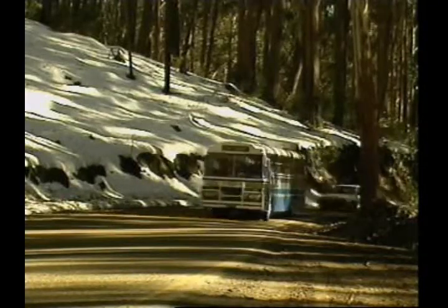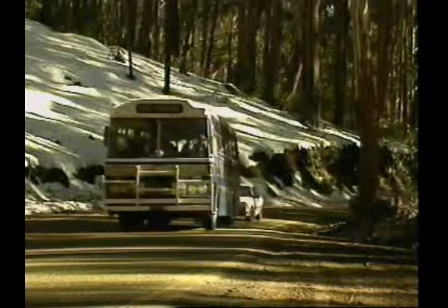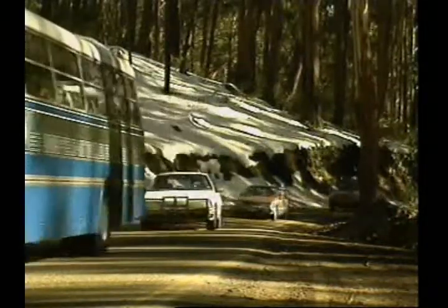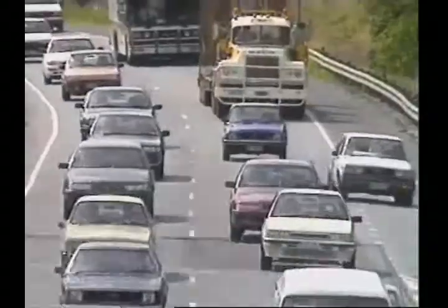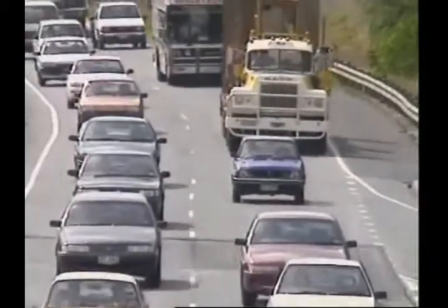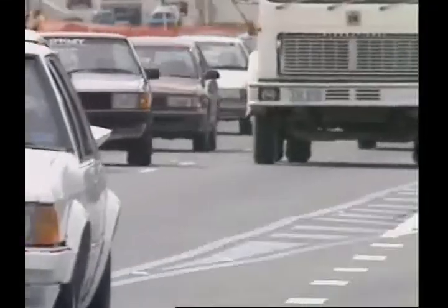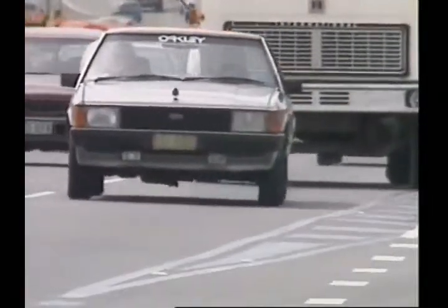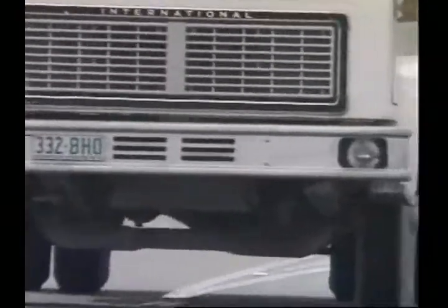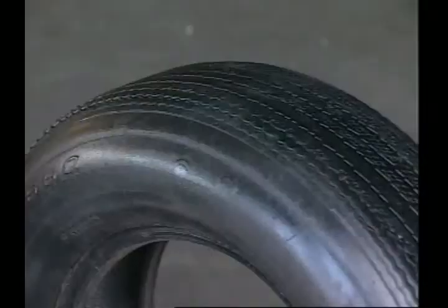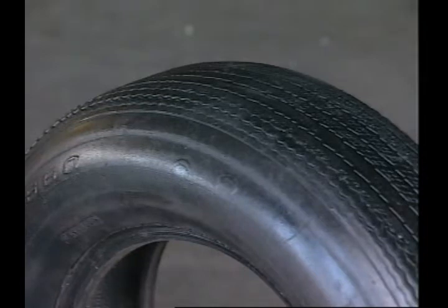However, during cornering, stiff sidewalls can distort the tread and partially lift it off the road surface, and that reduces the friction between the road and the tyre. Stiff sidewalls can also make a tyre run at a high temperature. This is because as the tyre rotates, the cords in the plies flex over each other, causing friction and heat. And a tyre that overheats can wear prematurely.